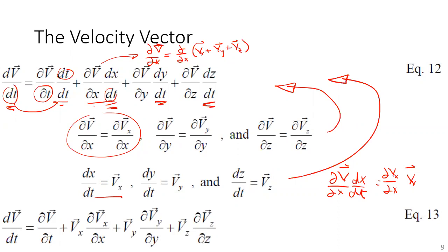This one is saying, look at one location and tell me what happens with the velocity vector at that one location. So if you have what's called steady flow, you have one velocity at this location, and that's happening now. It's happening 10 minutes from now. It's happening 10 years from now. Steady flow means the velocity is constant, or the discharge is constant at that location.